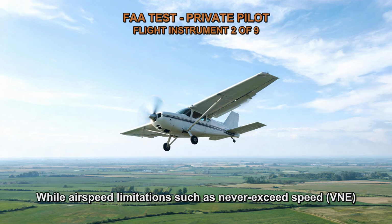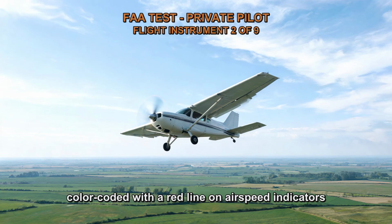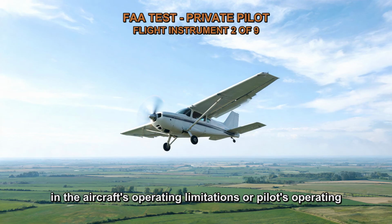While airspeed limitations such as never exceed speed, VNE, and maximum structural cruising speed, VNO, are often color-coded on airspeed indicators to indicate their limits, maneuvering speed is not usually color-coded. Instead, it is provided as a specific value in the aircraft's operating limitations or pilot's operating handbook.